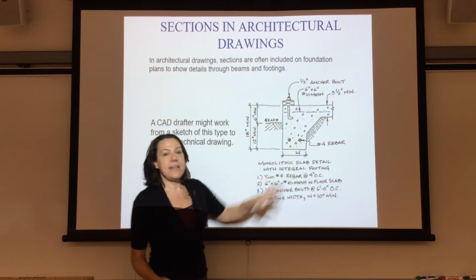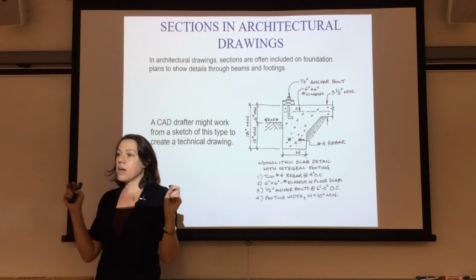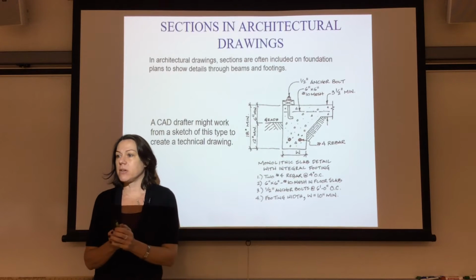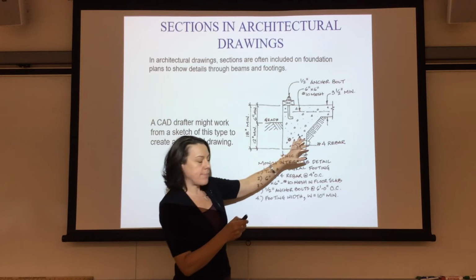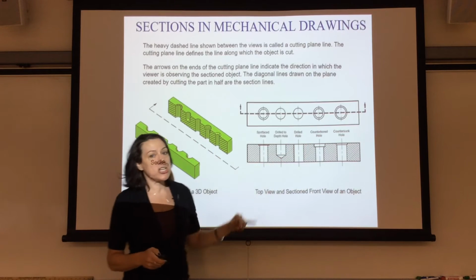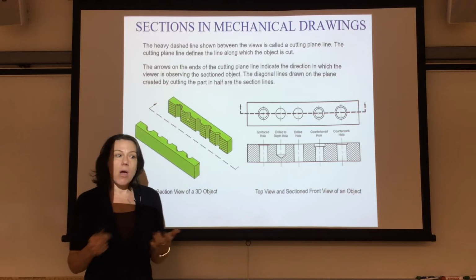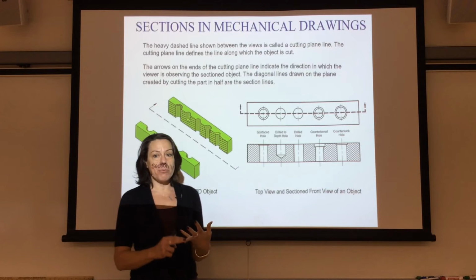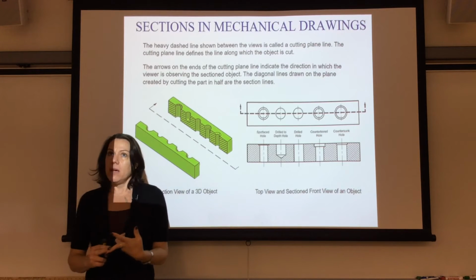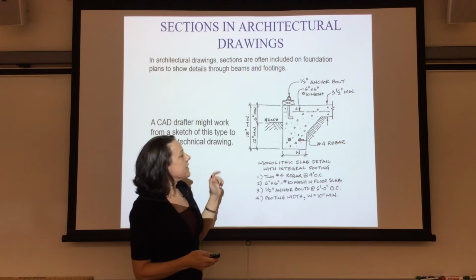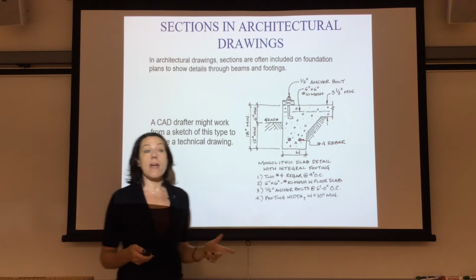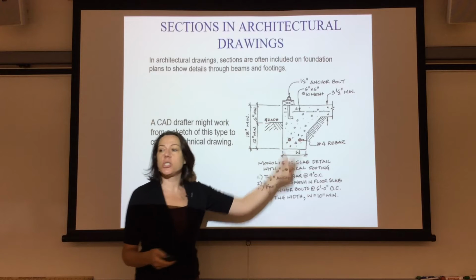This hatching now becomes showing you that it's concrete or it's some type of material. Okay? This section, and I'm going to go back one, these hatchings represent something specific, whether it is steel, brass, cast iron, concrete, earth, sand, whatever. We use hatching to describe something.